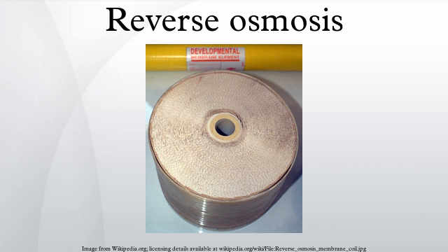Current Israeli drinking water standards set a minimum Ca level of 20 mg per liter. The post-desalination treatment in the Ashkelon plant uses sulfuric acid to dissolve calcite, resulting in Ca concentration of 40 to 46 mg per liter. This is still lower than the 45 to 60 mg per liter found in typical Israeli freshwaters.